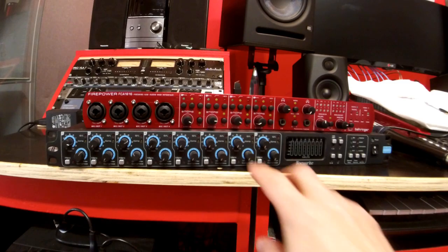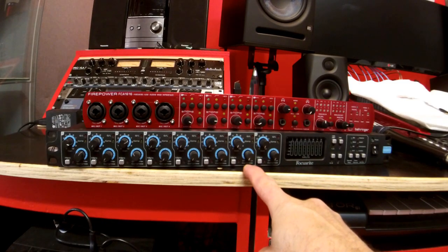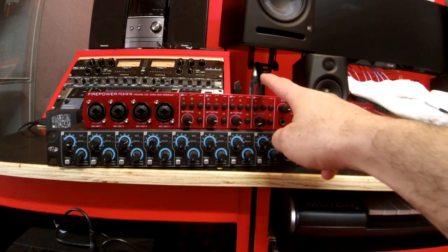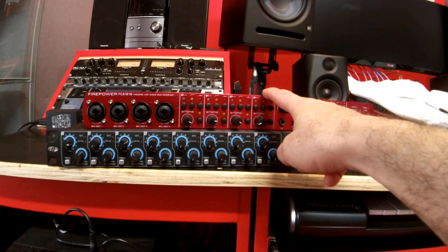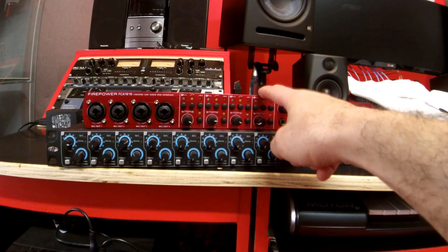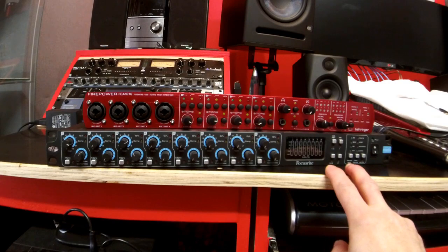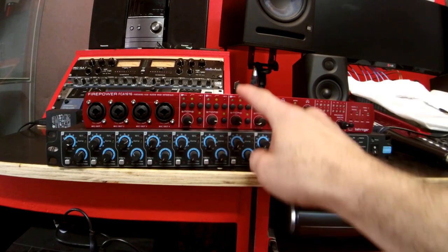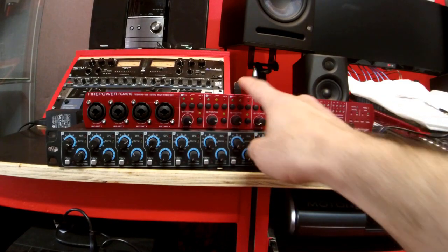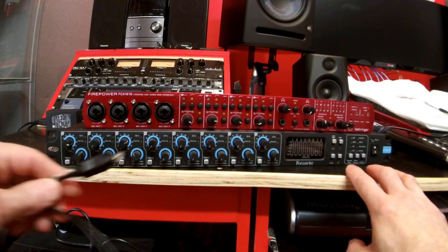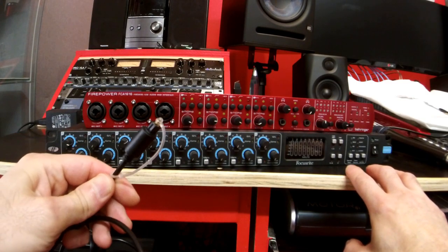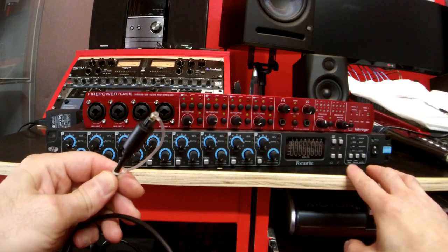ADAT extension modules like this one don't connect directly to your PC via USB. They connect to already existing audio interfaces that connect to your PC with USB or Firewire. The way the external modules connect to your audio interface is with these cables here. These are optical cables,